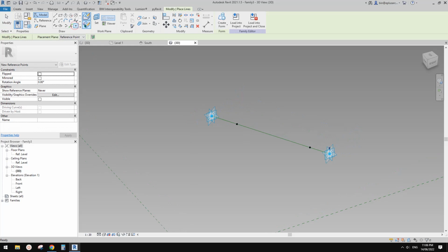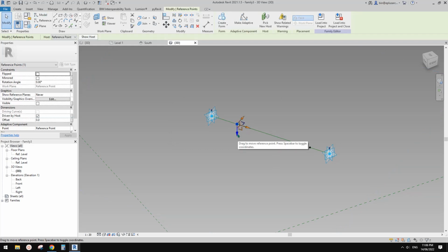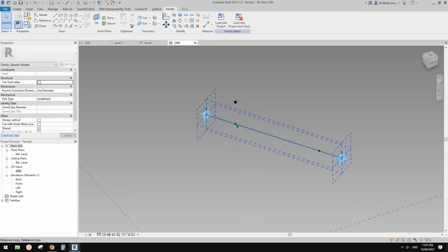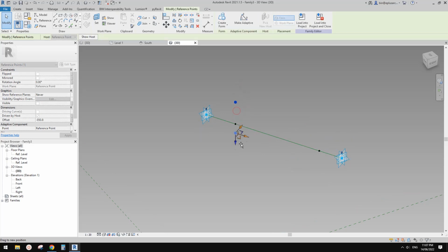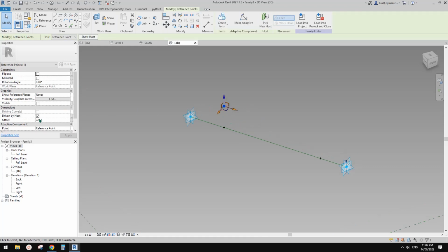So then next, create a point, use draw on work plane, set work plane, pick, select this point, place it on this point, and okay. So select this point. I need to go up, which means it's a negative. I prefer this to be positive. So maybe I'll just drag this down to have a positive offset, and then this one we just need to rotate by 180 degrees, so it will go up with a positive number.